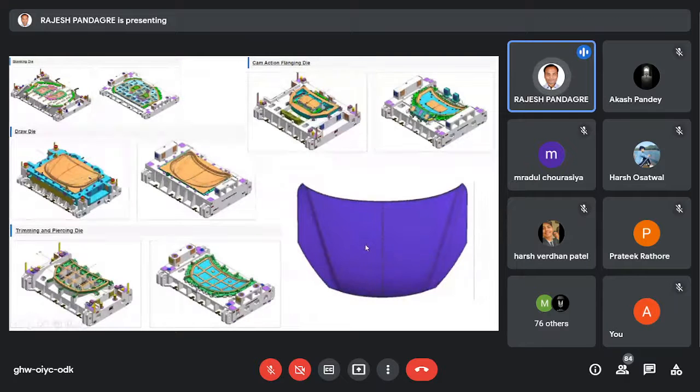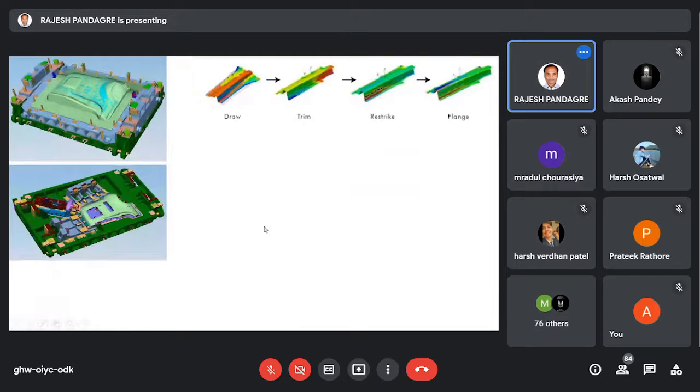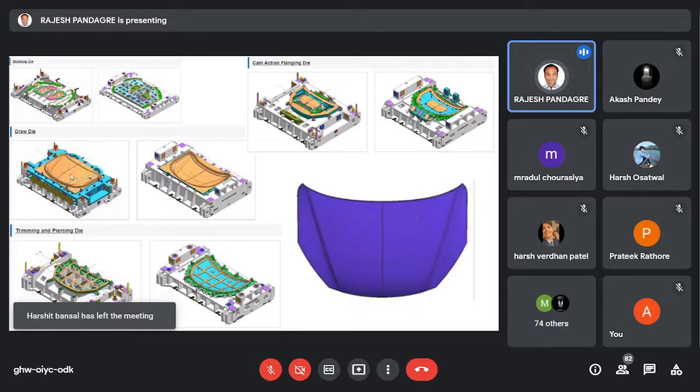So those surfaces will go to NC programming. The NC programmer will program on that, so that the casting we had received earlier will be pre-machined and then remachined. Remachined means fine machining, we call it. So fine machining, the milling operation, will be there. Once NC programming is done, that program will be fed to the CNC. So in the CNC, milling operations will happen.